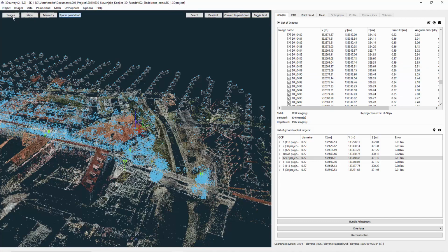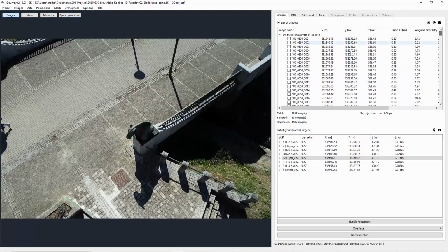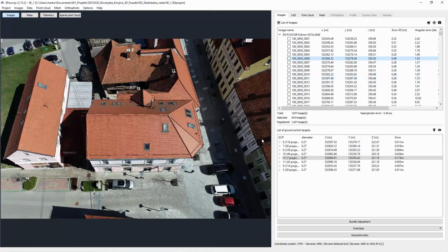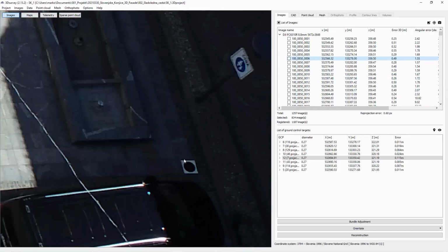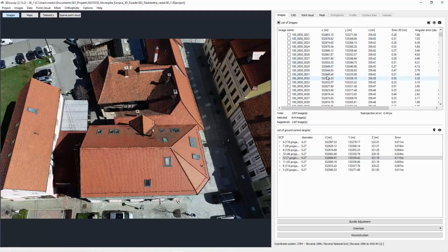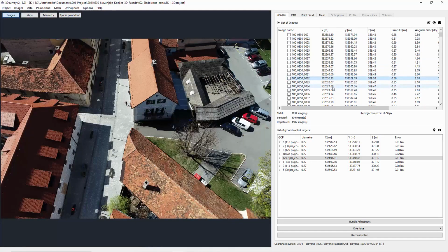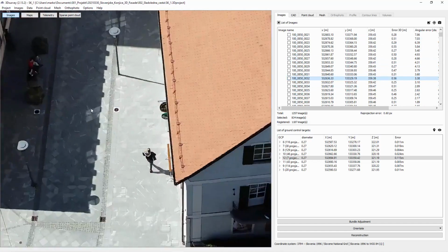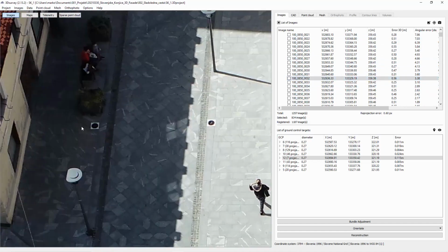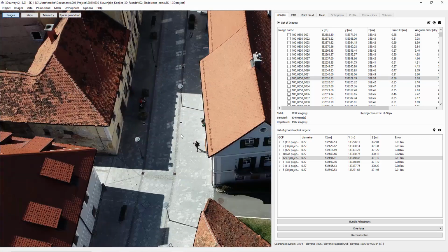Maybe just quickly show you, I also use 3D survey ground control points here, and you can see one from 35-meter height. Let's try to find another one. Okay, here are two actually. I just lay them on the left and right side of the road and that's it. Standard setup, and accuracy perfect. Then reconstruction was done here on high level.